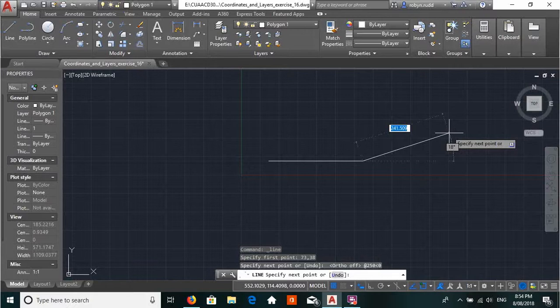So you'll see that it's provided you with an angle there of 135 on the inside. To get that angle, you can do it two ways. You can actually prompt it by giving it a length, so use the at button before the unit, so at 60, and to create that angle, it's actually at an angle of 45, because 180 minus 135 is 45. So you then type in at angle of 45.